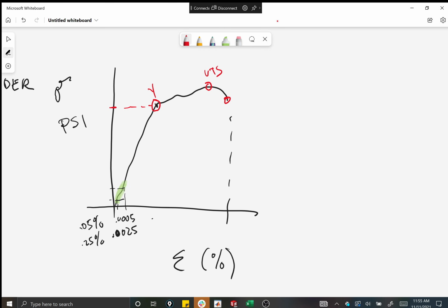It's going to be the strain at fracture, or percent elongation at fracture is what we're actually calling it. So that's another potential quiz question. Percent elongation at fracture. And then the load at fracture, or stress at fracture, would be the Y value here. Okay.